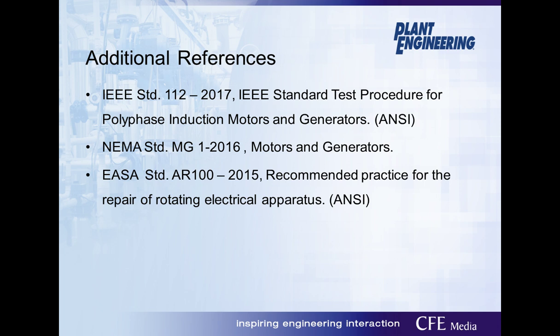You will see that I've listed a few of the standards that we have referenced today, along with a few additionals. The IEEE 112 standard for test procedures of polyphase induction motors and generators, the NEMA MG1 standard for motors and generators, and the ESA AR100 standard for recommended practices for the repair of rotating electrical apparatus are all great references to use when troubleshooting AC induction motors and looking for specific guidelines.